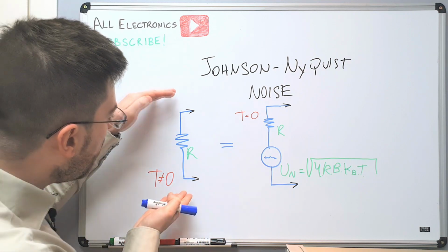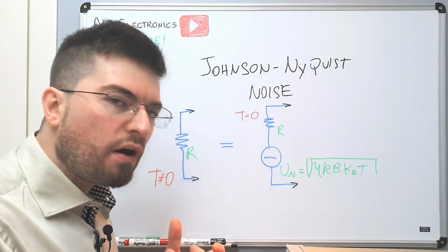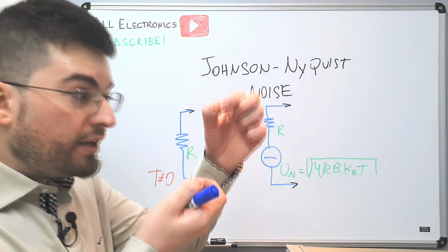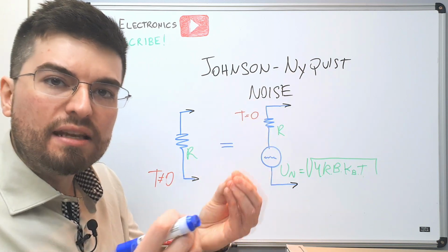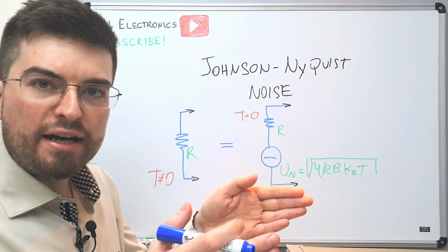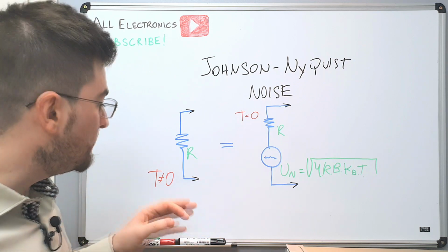And it is the noise a resistor produces by the fluctuations of the electron from the thermal activity. I'm not talking only about a physical resistor, a component, but about any material that has a resistivity that defines a resistance over two defined points and that presents itself in a temperature higher than 0 Kelvin.